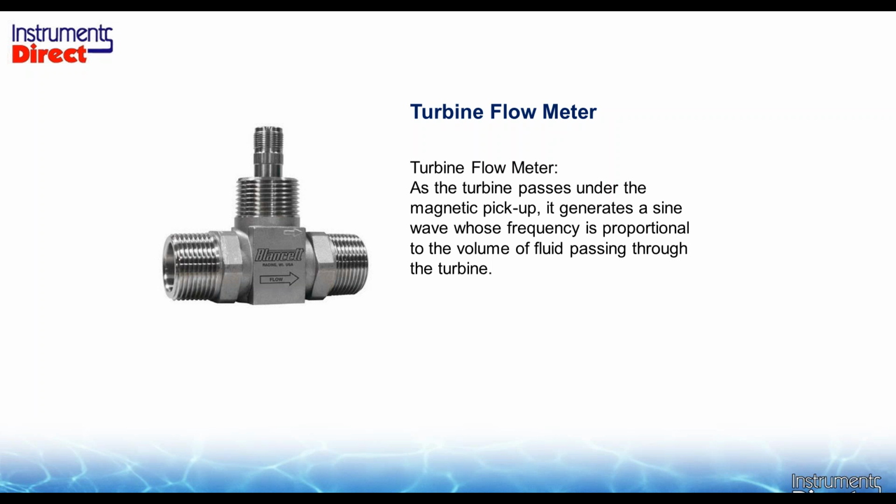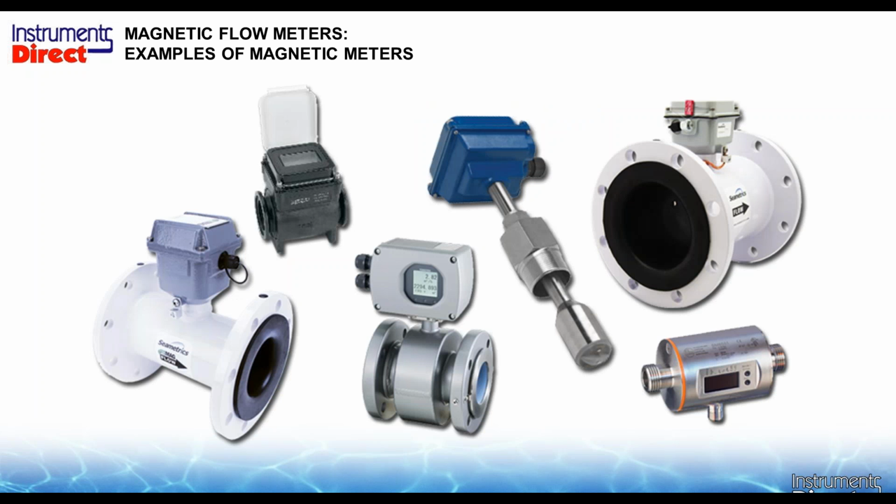And now we move from the traditional water meters more into the process meter, and the turbine has different variations. It comes in sanitary packages and non-sanitary packages. So now you're wandering into the arena where you need to make sure you're at the right specifications and the right certifications for the specific application you're looking for.